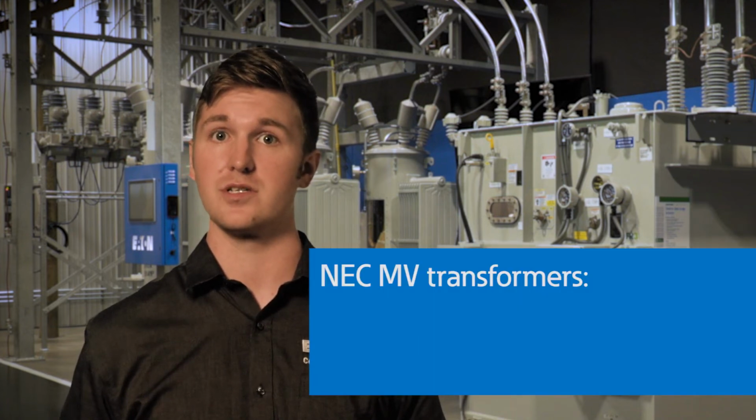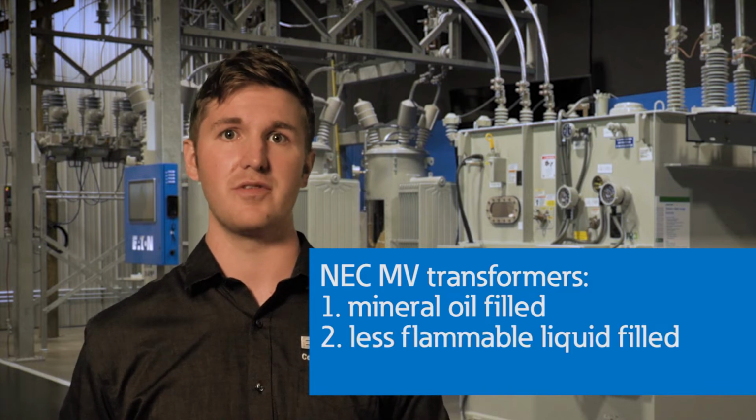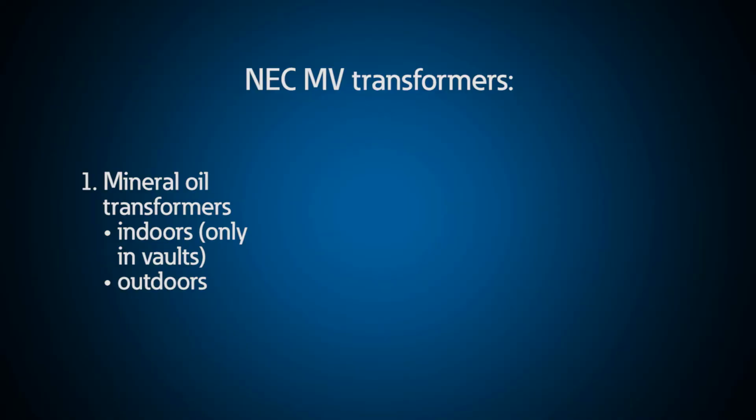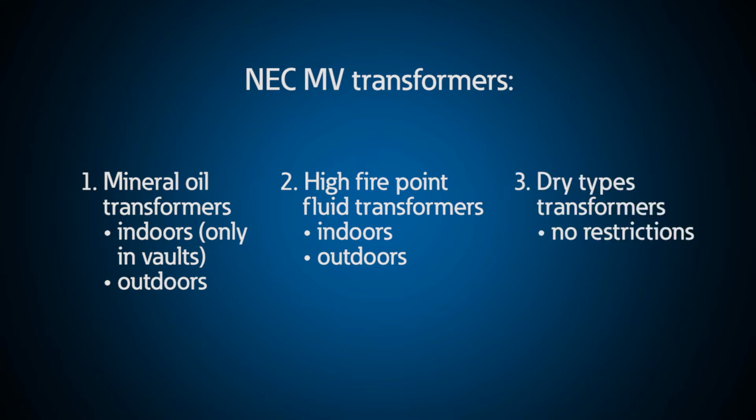The NEC splits medium voltage distribution transformers into 3 main categories: mineral oil filled transformers, less flammable liquid filled transformers, and dry type transformers. Mineral oil transformers may be installed outdoors or indoors, but only in vaults when installed indoors. High fire point fluid insulated transformers may be installed indoors or outdoors without restrictions. Dry transformers may be installed without restrictions.